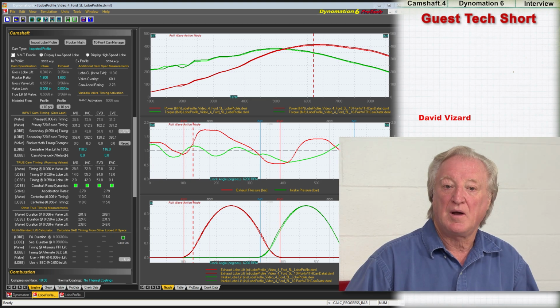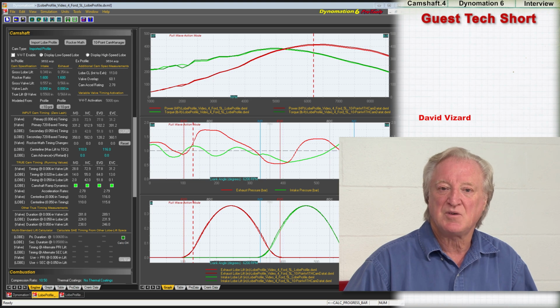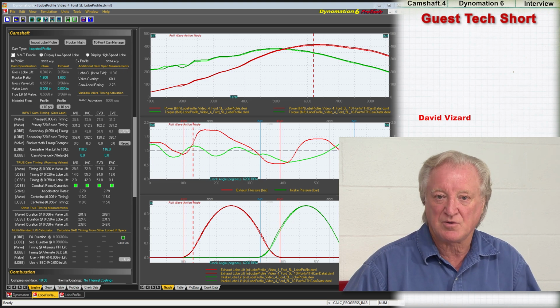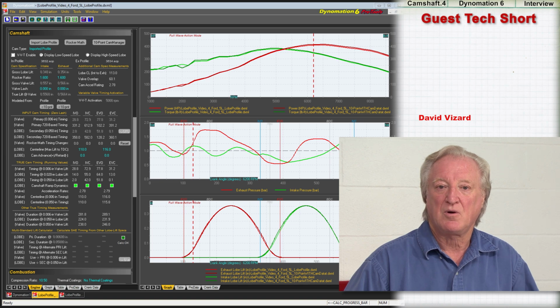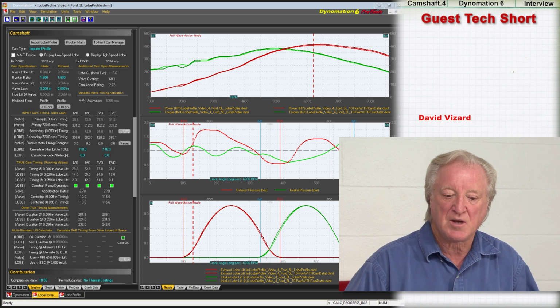During World War II and the time leading up to it, the aircraft industry did an immense amount of testing on camshaft valve events, and the general consensus of opinion by even the late 40s is that the point the intake valve closed was the most influential in terms of where power occurred in the RPM range and by how much. But like anything, when you think you've got a clear-cut picture of it, you find that things move on and something changes in the equation, and that changes what you thought you knew about it. And that's exactly what's happened.